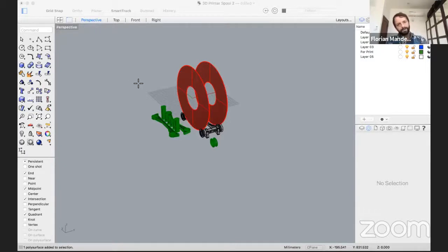And then you can create another point if you want, this one for example. It's asking you for the next point of the polyline, and you say 10 millimeters. Now it shows you, you can choose which direction it should go. If you hit shift, you can choose a 90-degree angle, or you can freely choose here. You can always modify it later. But this is how you would have created your first line. When you select it, it's highlighted in yellow.